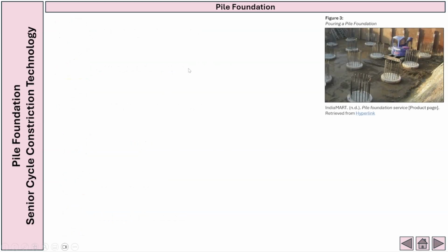When you're drawing your detailed drawings, just make sure that it is a scale 1 to 10 where you're dividing all of these measurements by 10. The first thing we're going to do is start off by drawing our pile, and the pile can be any depth. It really does depend on how deep the pile needs to go in order to reach sufficient bedrock. So for the purpose of this video, I've only made it 50 millimeters. It is a concrete pile indicated by our triangles.